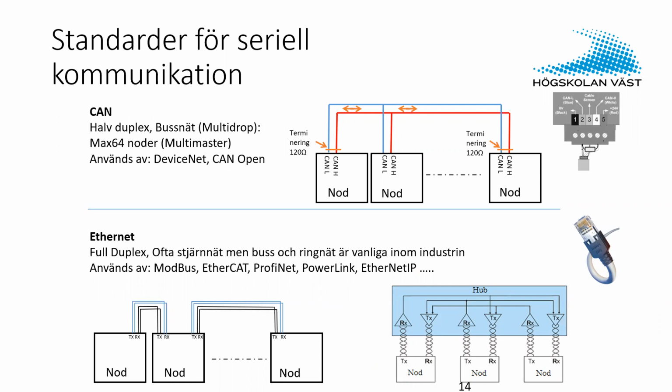Serial communications are very common. Actually, our normal Ethernet is also serial communication. And then we have the CAN bus as well, very common inside cars, but also in automation. You have CANopen and DeviceNet in factory automation. It's also half duplex. It's a bus network, 2 wires, and you will learn more about the CAN bus in the next week, actually. Next week, yes, with Eric.